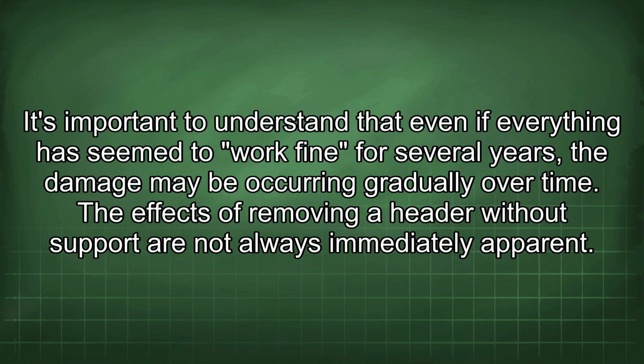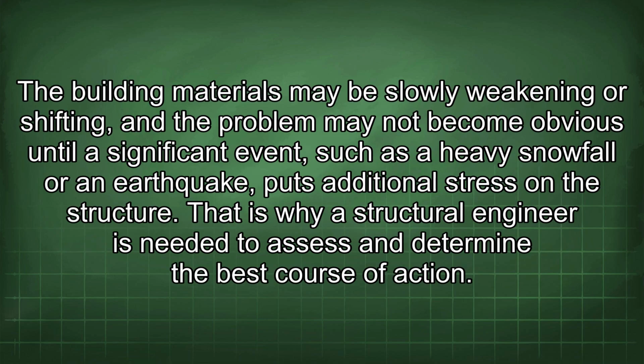It's important to understand that even if everything has seemed to work fine for several years, the damage may be occurring gradually over time. The effects of removing a header without support are not always immediately apparent. The building materials may be slowly weakening or shifting, and the problem may not become obvious until a significant event, such as a heavy snowfall or an earthquake, puts additional stress on the structure.